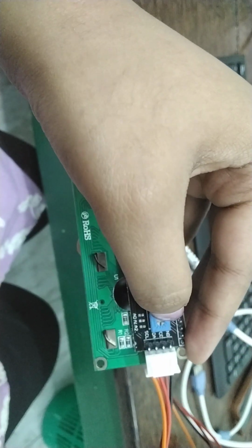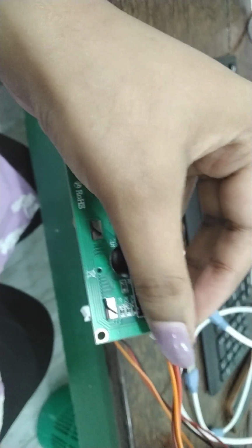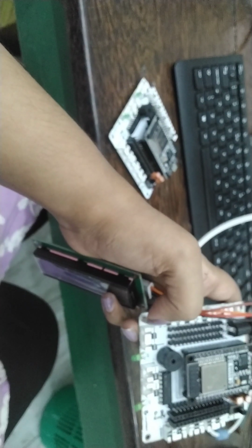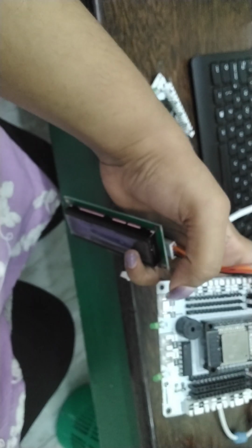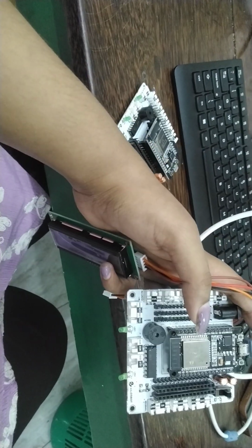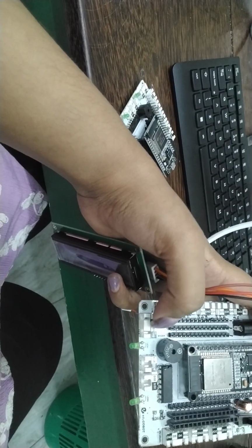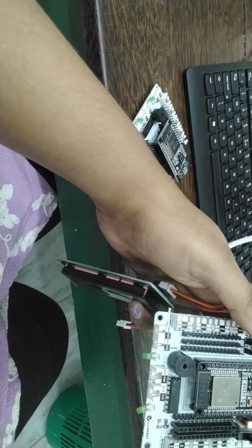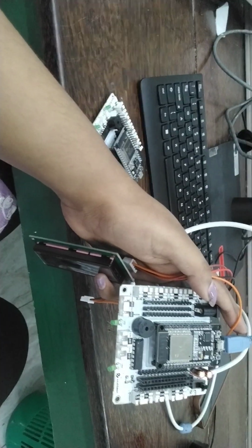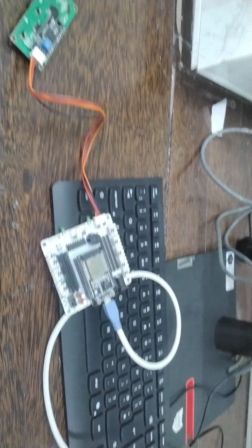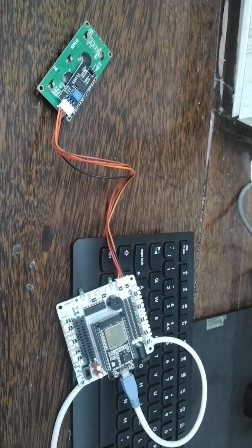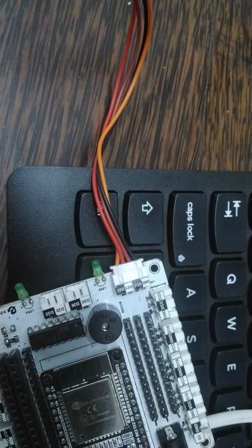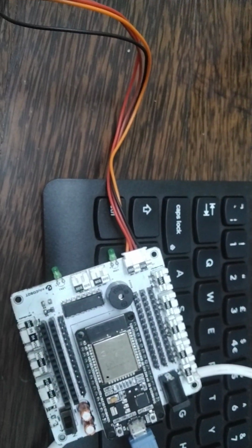Now we have to ensure that this GND, which has a black wire, is connected to the GND on the microcontroller over here. And for that reason, we are going to be using the one with the 4 ports, which is right here next to the buzzer. So we're going to connect these wires over here on GND, VCC, D21 and D22. But we have to make sure that the black wire comes on GND just as it is over here. So we are now going to connect the jumper wires to the microcontroller. Now our LCD is connected to the microcontroller through the jumper wires over here next to the buzzer, right? And the black wire is on GND, which is the negative terminal.